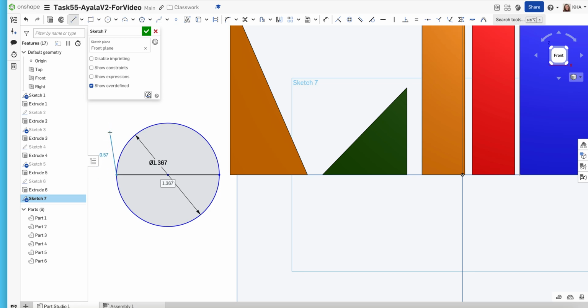I'm still in the line tool. I can press escape. The escape key will get me out. The other option is I could right click and choose escape line. And there I go. Okay, so we have drawn a circle, we have drawn a line coincident with the x-axis here to cut the circle in half.